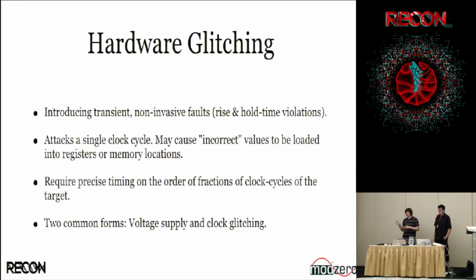But all of these things work on embedded devices. They're starting to go away on smart cards to a certain extent because they're protected against them. But let's say you have a crypto coprocessor on some device, which is decrypting some stream coming in, and you want to see if you can somehow force it to load something or dump more memory as it's doing a printf, etc. What you can do is you can glitch it.